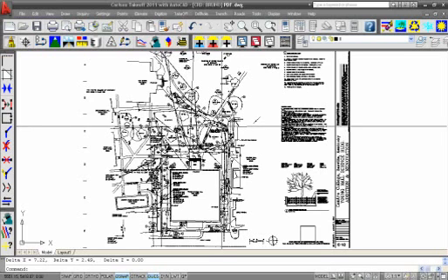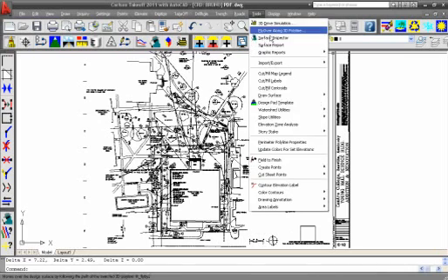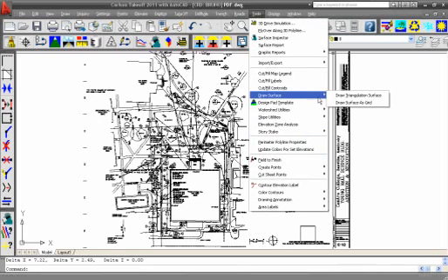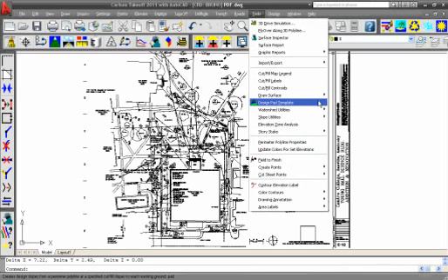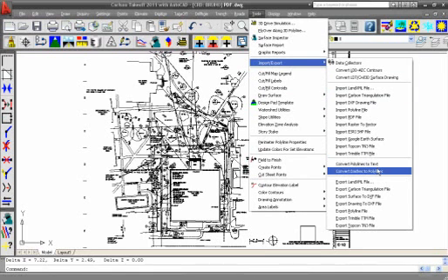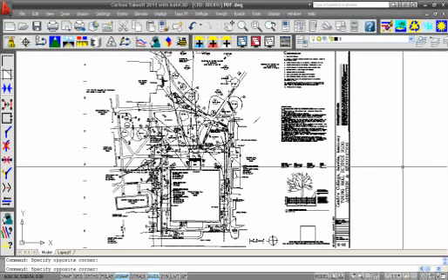So those are some of the new tools that we've created for working with PDFs: the ability to recognize the layers and different colors in the drawing and put those out to layers, the ability to process text and dash polylines into continuous lines, and to scale the PDF in a simpler fashion.